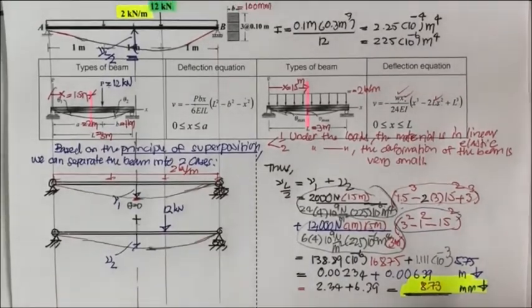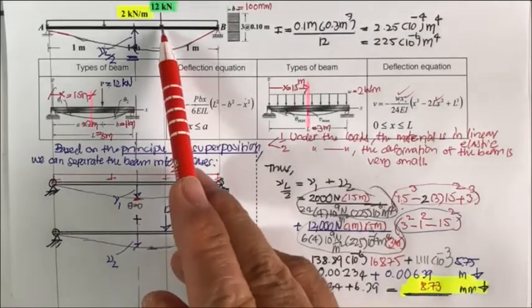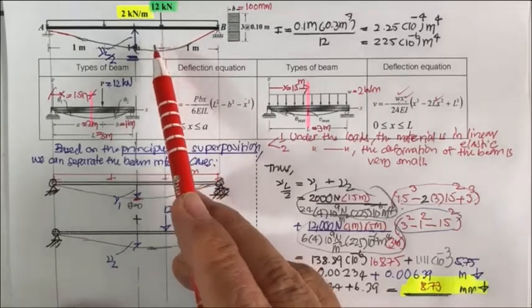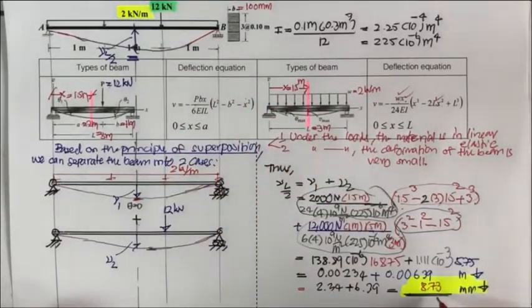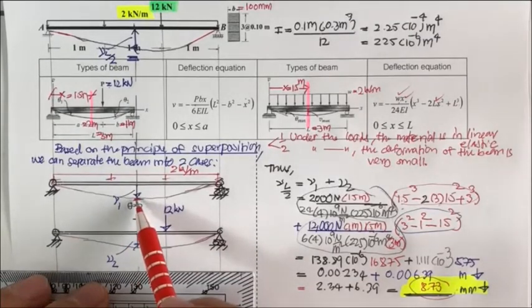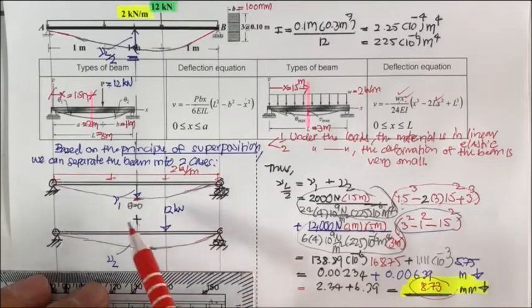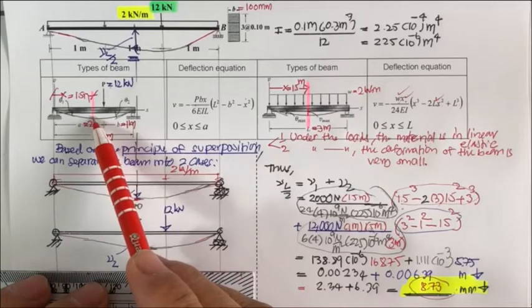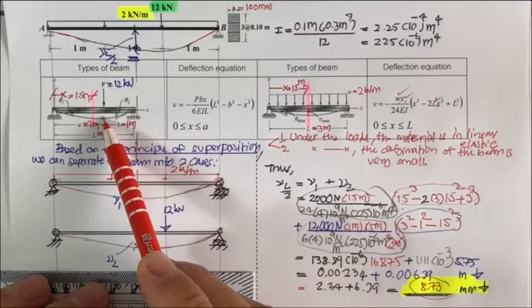And at this time, you may see the load is not symmetry. Okay, so what's going to be the next point that we should check to find the maximum deflection? Coming back to here, over here, the maximum is going to occur at the midspan, okay? And at the midspan, theta equal to 0. But for this one, the maximum deflection will occur between the midspan and the loading point.